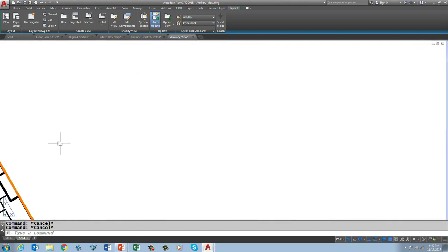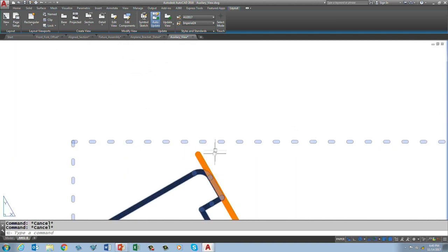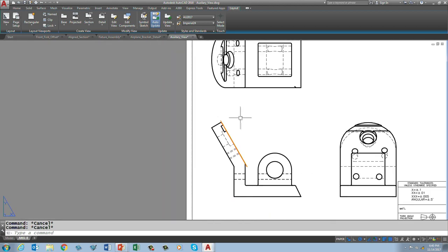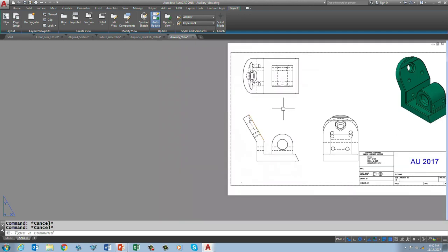The key part, though, is there's a little gotcha there because we have a little fillet in that corner, right? Well, it's actually technically a round, but of course AutoCAD doesn't have the round command, right? They have the fillet command. But anyway, what I want to do is I want to go in and create a full section. So I'm going to go into section, I'm going to go to full. Well, no, I'm not going to go full.